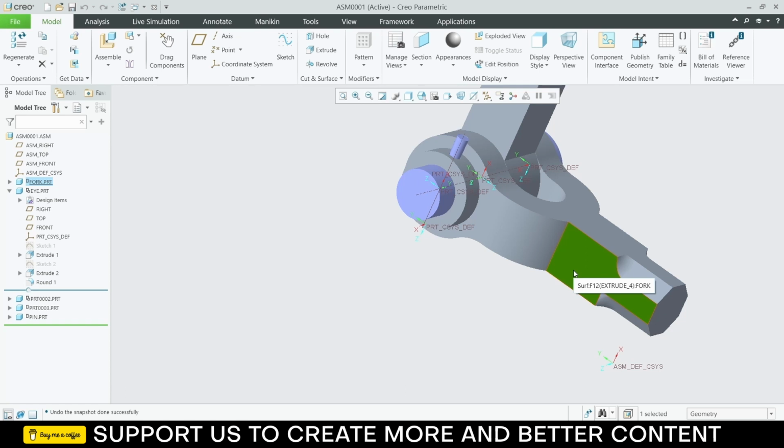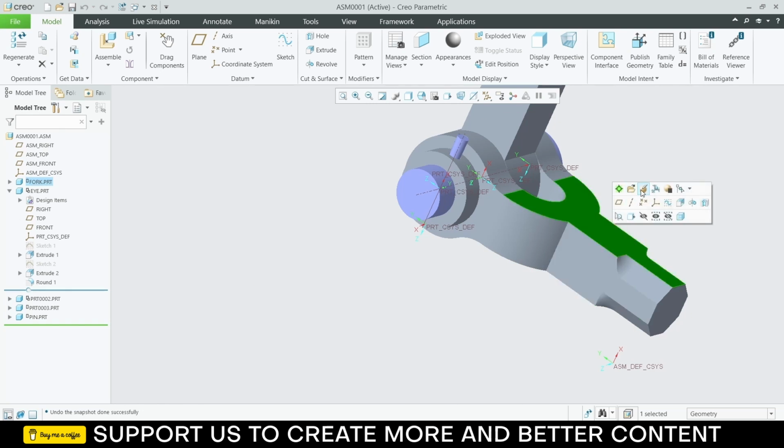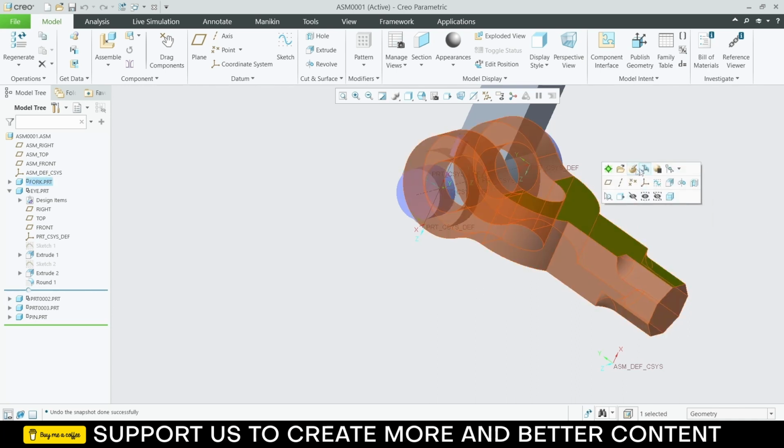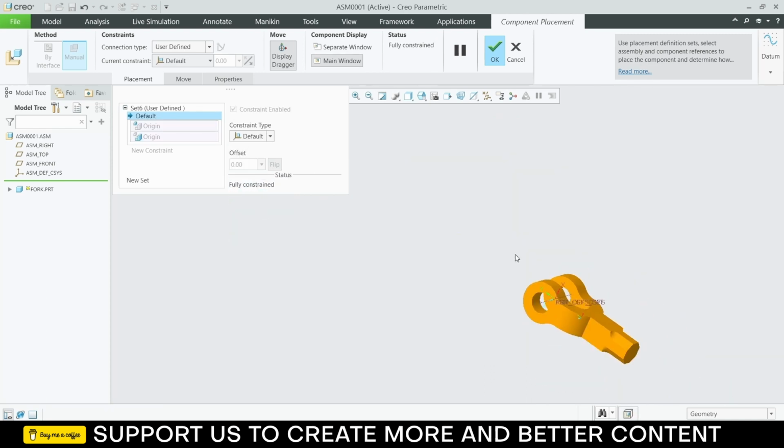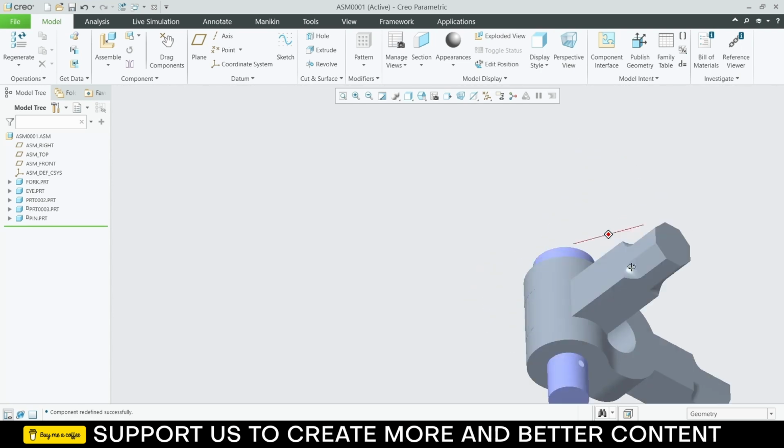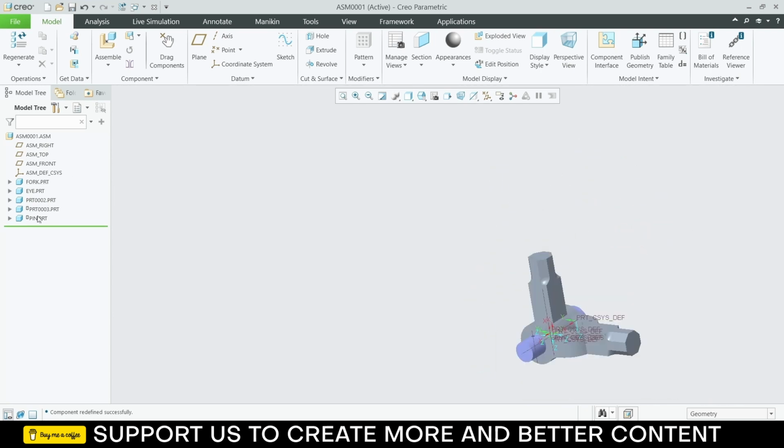Assemble, select the first part. Now to fix the first part, always go to placement, select default and say OK. The first part is fixed. Second, now I have to fix this part. So click on it, click here and click on placements, default. Click OK. Yes, okay.